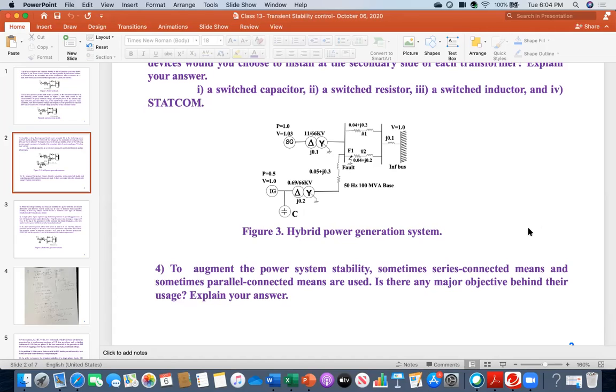That's why in some power grids, all over the world, as a protection means, you will notice there are series connected devices, like the fault current limiter. Its name is fault current limiter. Clearly, that is reducing the fault current magnitude, and then the voltage and active power are coming back to the original position. According to this concept, for parallel connected devices, as Amani mentioned, it will control the voltage first, then active power, and the system stability will come back. So that is the objective.